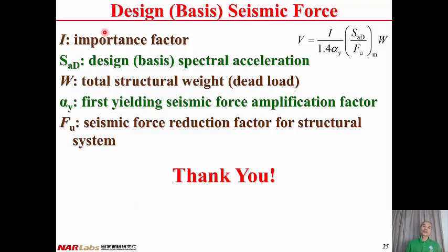And in this lecture, we talk about design seismic force, and the design seismic force is determined by importance factor I here, design basis spectral acceleration SAD here, W, the total weight of the structure, that's the dead load of the structure, and alpha Y, the first yielding seismic force amplification factor here.